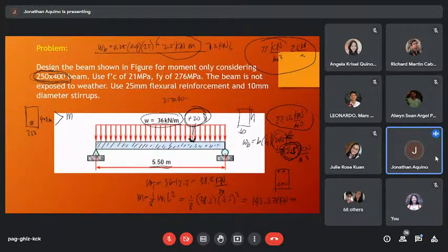So let's say, for example, considering singly reinforced rectangular beam, the moment capacity is greater than M, meaning singly reinforced rectangular beam. But if your moment capacity is less than the actual moment of 145.578, so use doubly reinforced rectangular beam.